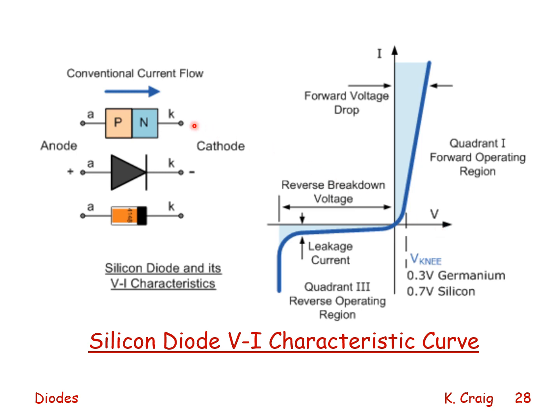Here is a diagram showing the P-type and N-type materials that comprise the diode, with the anode and cathode. The anode being plus, cathode being minus. We see the bar in the schematic corresponds to the dark circle on the actual device. That's how we identify anode and cathode.